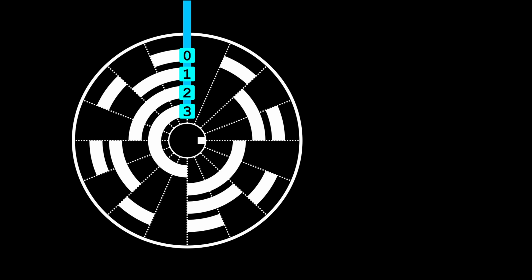It also might not be obvious that it is in any way useful. The classic use case is for rotary encoders. Say you want to know the angular position of a wheel, accurate to 1/16 of a full rotation, or 22.5 degrees. You could use 4 optical sensors, and attach a disk that has 4 concentric circles broken into black and white sections for the sensors to read.